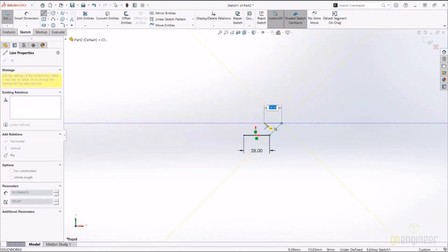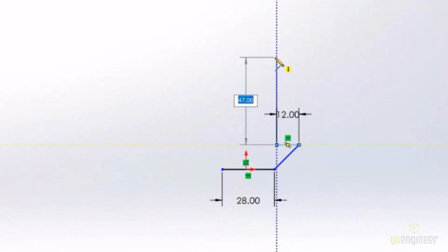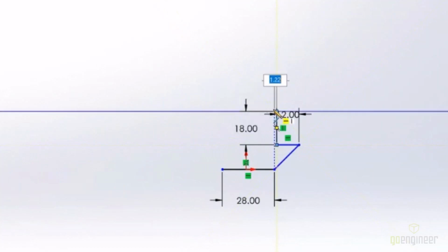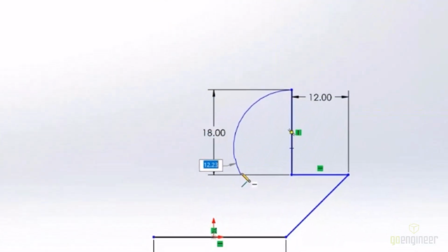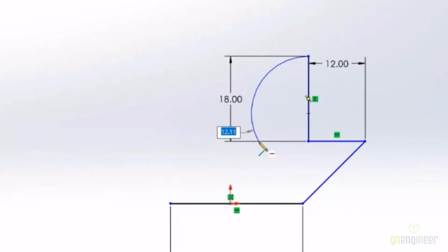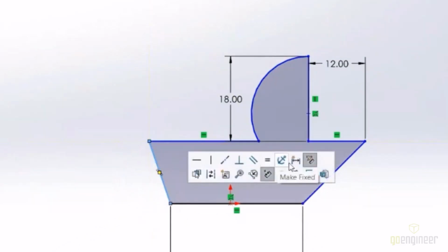Now in this one, I want the horizontal. So I do snap down to that automatic horizontal sketch relation. And then I go ahead and type the value that I want. Pull up, type a value, enter. Hover to switch the arc. I don't want the radius, so I just ignore that. Click down and click down and click down.